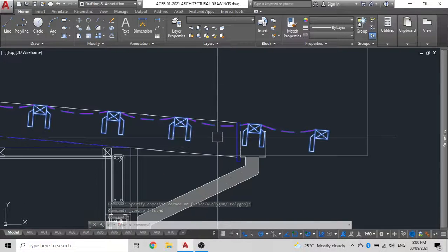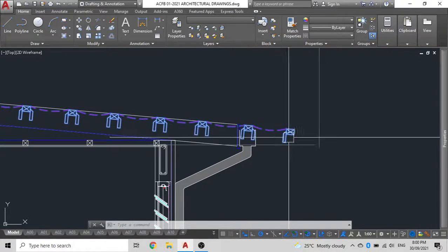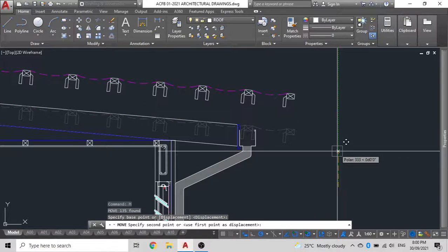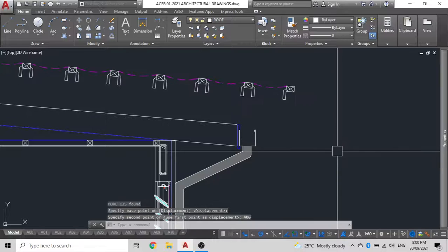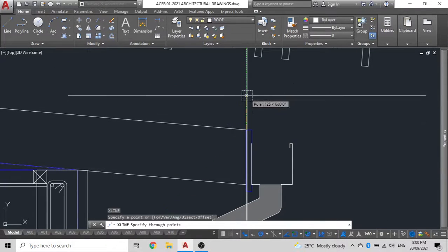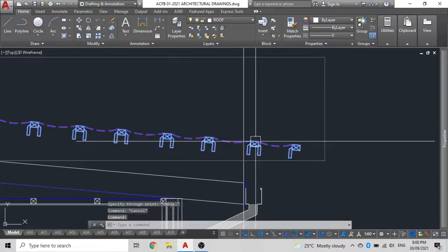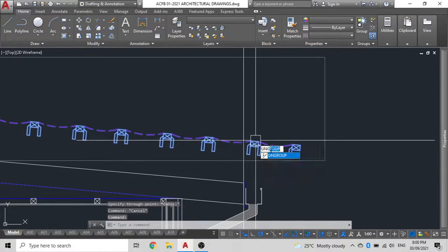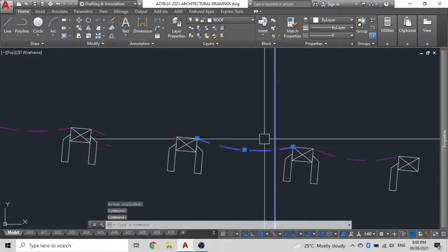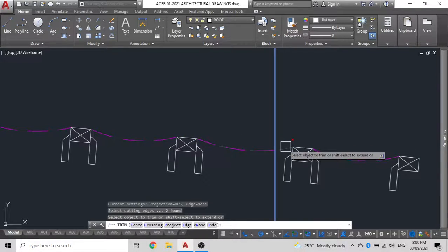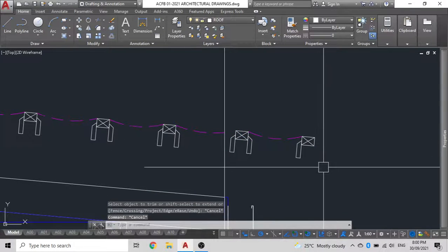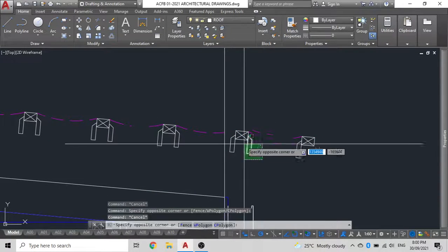So what I'll do is readjust a few things here. I'll move this up by a distance of 400. Then I'll shoot up one of my X lines like so, ungroup my setup, then trim off the unnecessary items. Now I have shown in another video how we can use the AutoCAD commands to do your drafting work.